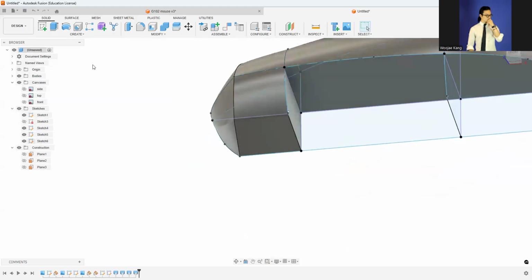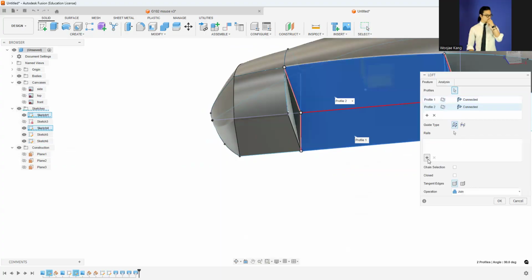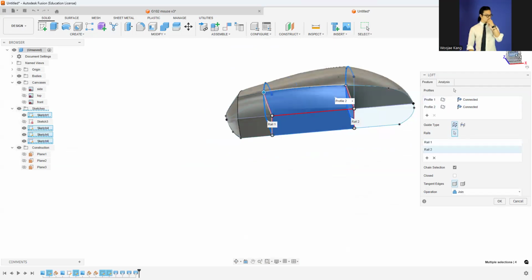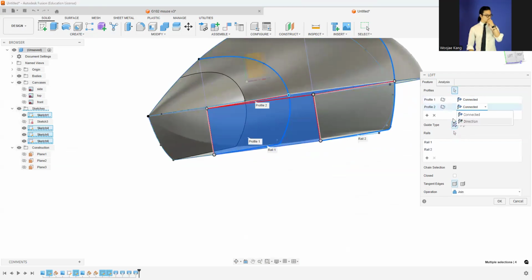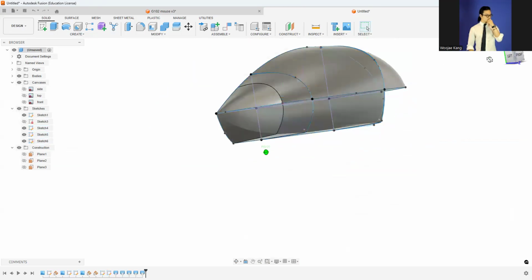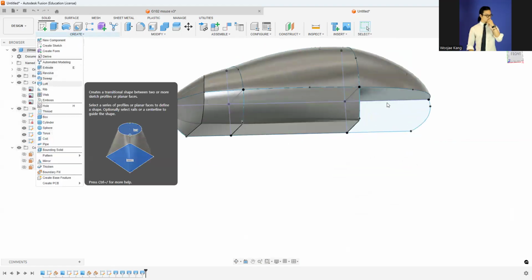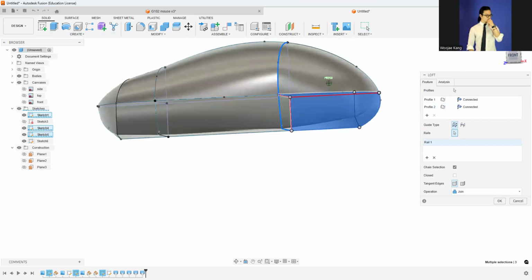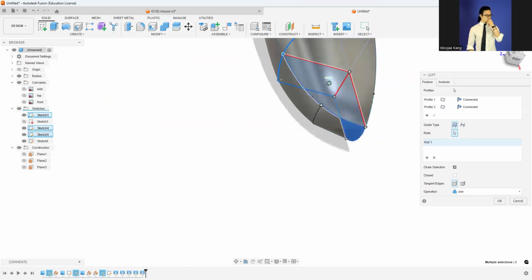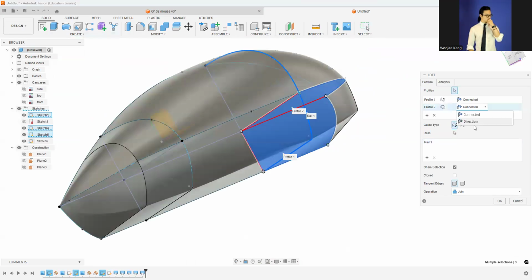Okay, and from here again using loft, select the side and the top and select the guide rail. I think from here you can also use the chain selection for here and the behind. And again, since we select the profile on the top, make sure that it's also in direction, so it's smoothly connected. And finally, select the loft for the side, top, rails, and it's smoothly connected.